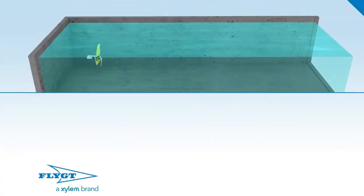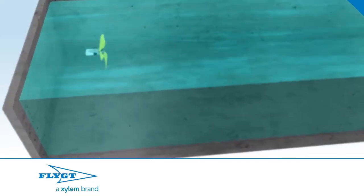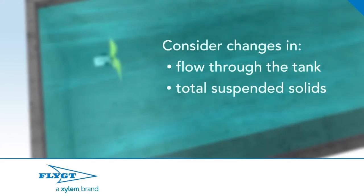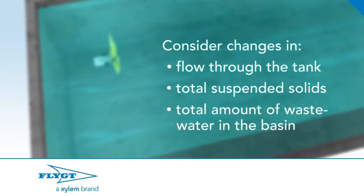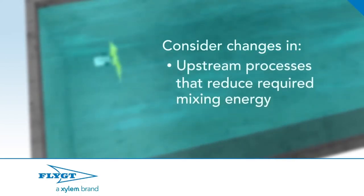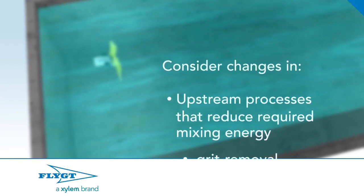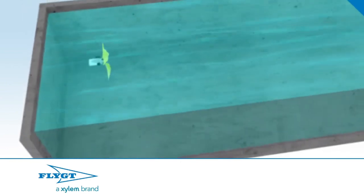So when is it appropriate to slow the mixing speed? You must consider changes in flow through the tank, the total suspended solids, and even the total amount of wastewater in the basin. All these changes, whether they happen hourly, weekly, or seasonally, are opportunities to save energy and reduce your carbon footprint while extending service life and improving reliability. Variable speed mixers have other advantages as well.